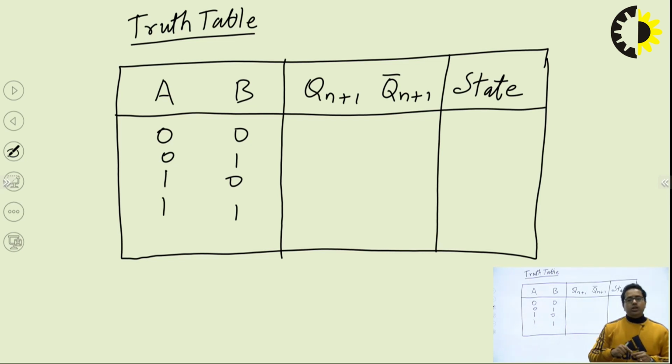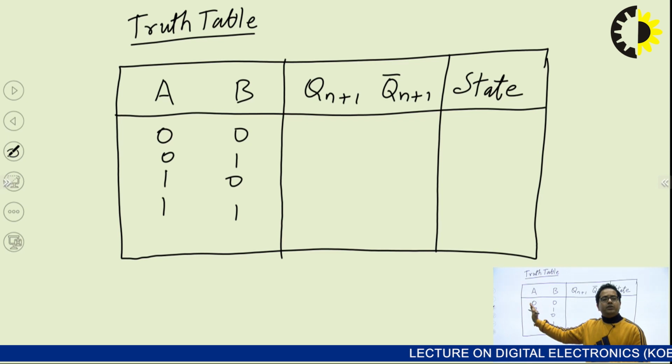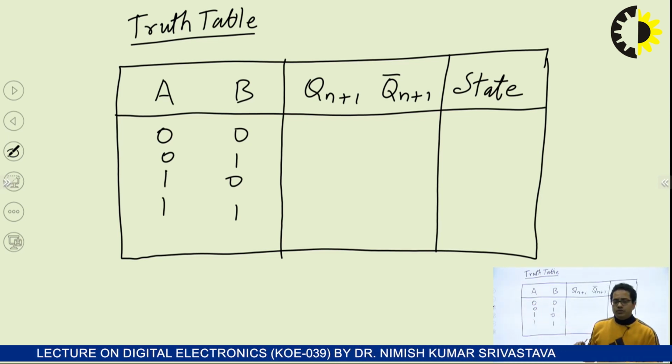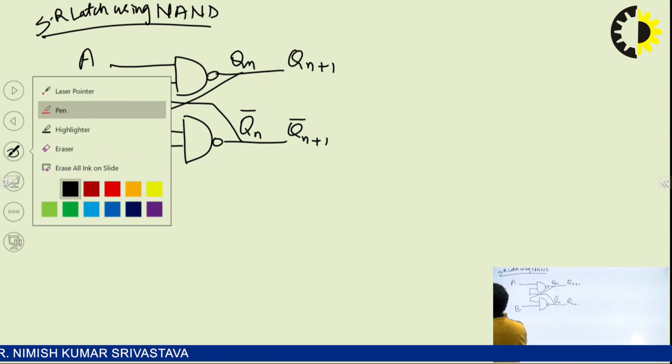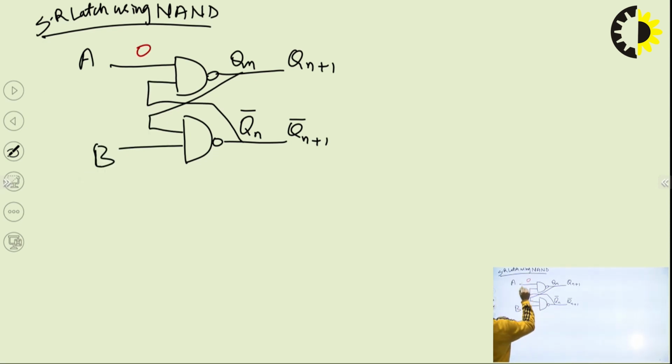Now, what is the value of input that I should consider for the NAND gate, so that without knowing the value of other input, I can easily predict what will be the output? So that value is 0, because if you are giving one terminal value as 0, irrespective of the other terminal value, you can directly predict what will be the output. It will be 1. So concentrate on the input combinations for which we are having a 0.